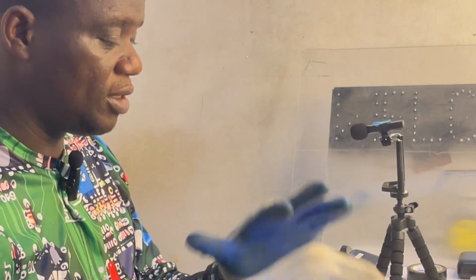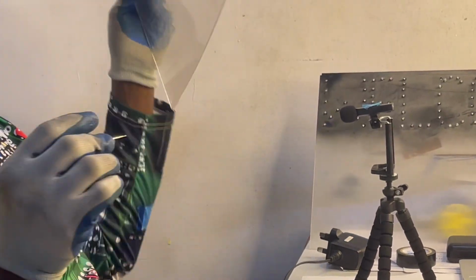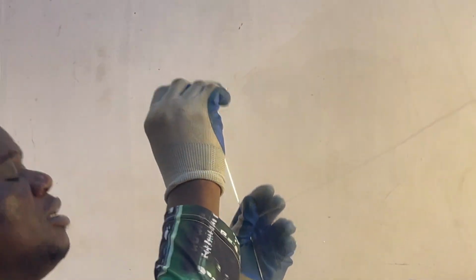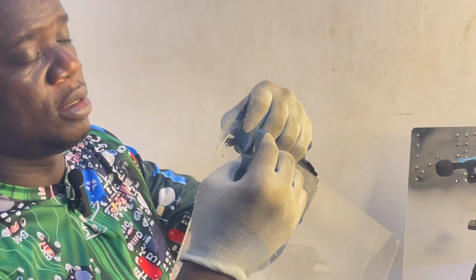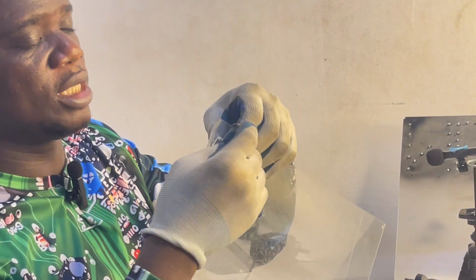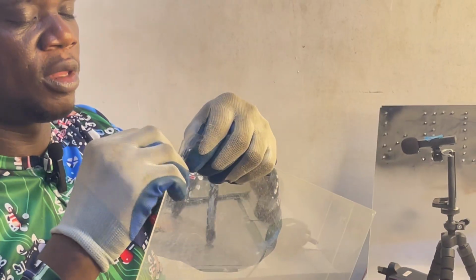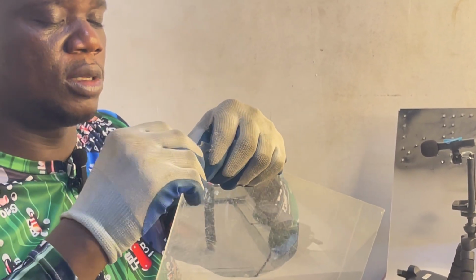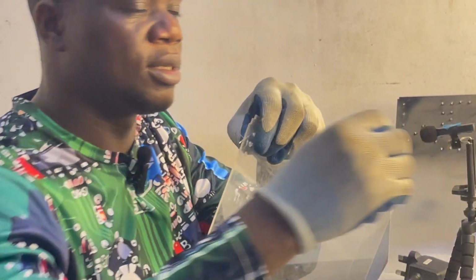So having said that, you start inserting your LEDs. You insert it. You put all the anodes one side, all the cathodes one side. As you are forming them, when you put it, you just drag the anode this way, drag the cathode that way. You pick another one.